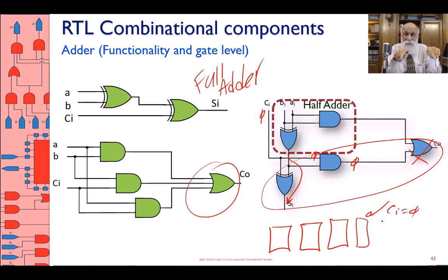Okay, but then instead of using full adder, if you use half adder all the way through, then that creates an incrementer for you, a circuit that adds a 1 to your input. Remember, when I was doing two's complement conversion, when I was doing the absolute value circuit, when I complemented the whole number, I added a 1 to it using an incrementer.